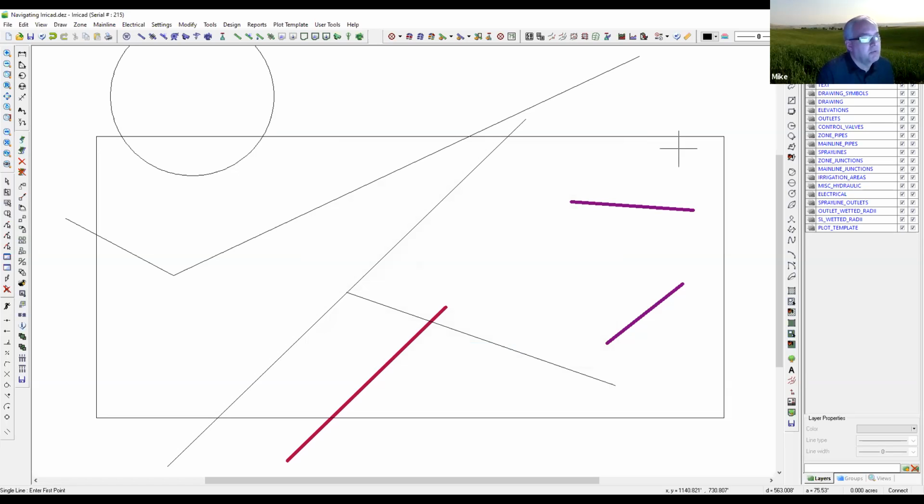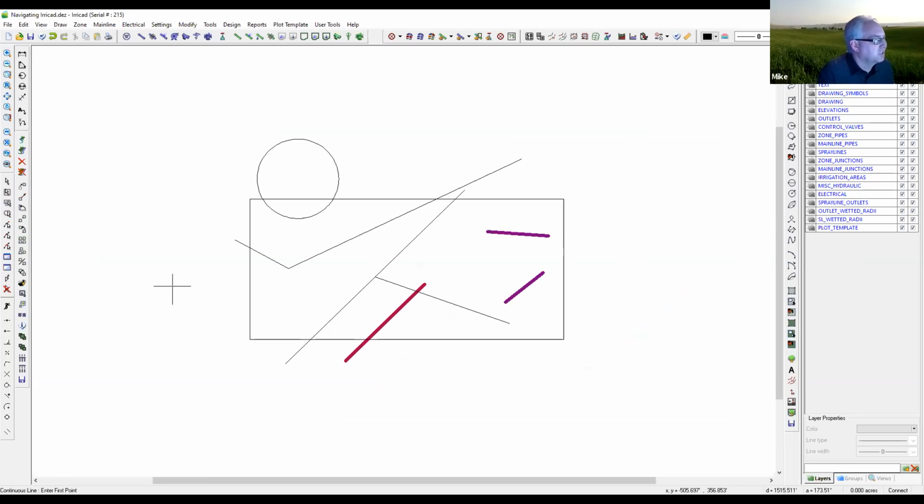And then we want to talk about polylines real quick. Let me zoom out here a little bit and give myself a little bit more space. A polyline is essentially a continuous line instead of a single line. So if I go around clicking, I can trace a boundary or create a specific shape that I want to. If I accidentally click over here and didn't mean to, a valuable tool under the right-click menu is what we call undo vertex. If I hit undo vertex, it's going to back me up. It'll continue to back me up as many times as I invoke it.